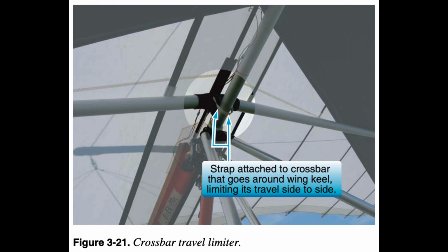Ground adjustable trim systems. The most common ground adjustable trim system, and typical of most aircraft, is moving the wing attachment hang point forward for faster trim speeds and aft for slower trim speeds. Each manufacturer has different hardware, but the basics of sliding the carriage wing hang point forward and backward on the keel is similar for all. As an example, moving the hang point at the furthest aft position to the furthest forward position could speed the wing up 20 knots. This in turn moves the control bar position back to a new hands-off trim speed.